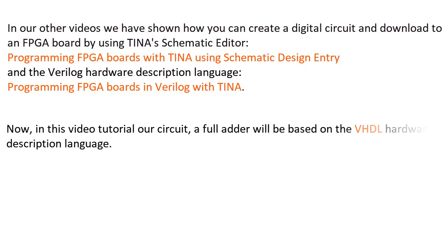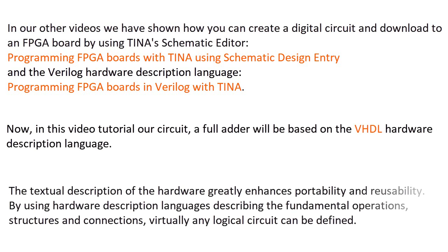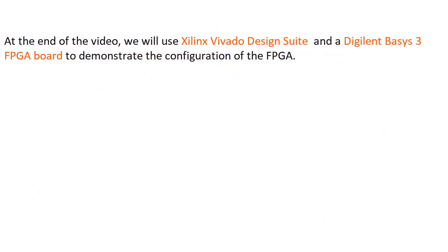Now, in this video tutorial, our circuit, a full adder, will be based on the VHDL hardware description language. The textual description of the hardware greatly enhances portability and reusability. By using hardware description languages describing the fundamental operations, structures, and connections, virtually any logical circuit can be defined. At the end of the video, we'll use Xilinx Vivado Design Suite and a Xilinx Basys 3 FPGA board to demonstrate the configuration of the FPGA.